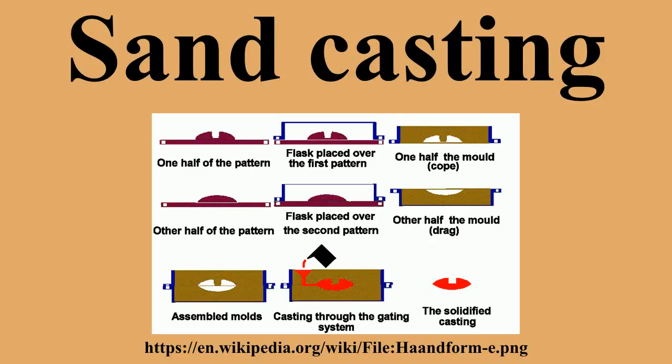The metal to be cast will contract during solidification, and this may be non-uniform due to uneven cooling. Therefore, the pattern must be slightly larger than the finished product, a difference known as contraction allowance. Pattern makers are able to produce suitable patterns using contraction rules. Different scaled rules are used for different metals because each metal and alloy contracts by an amount distinct from all others. Patterns also have core prints that create registers within the molds into which are placed sand cores.